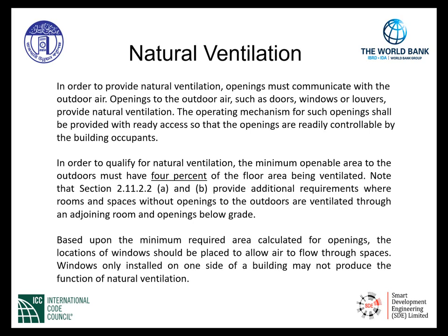Natural ventilation is given here. In order to provide natural ventilation, openings must communicate with the outdoor air. Openings to the outdoor air, such as doors, windows, or louvers, provide natural ventilation.